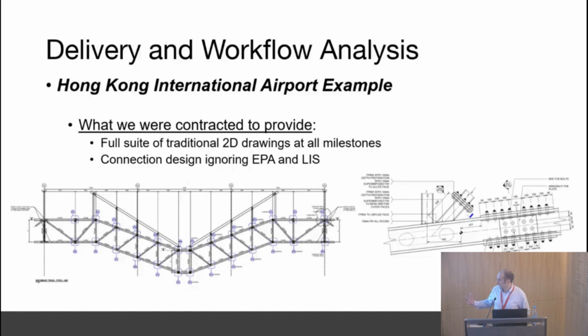We're responsible for the connection design as well. We've had to draw all the connections, but we've done that in the absence of doing an erection phase analysis, so it ignores all the locked-in stresses. So in reality, that will be thrown in the bin in 6 months' time, and the contractor will be redesigning it. So really, what is the point in doing that?